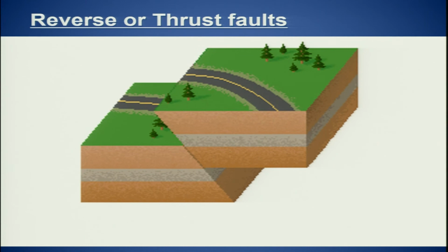Now coming to the reverse fault deformation. So please recall the section which I was showing from the Kobe earthquake, that we have the block has moved up and we have the high angle fault, and this block has moved up, and so you can show the direction something like this. Okay, this is down, and this remains the stationary wall, or we can say the foot wall, and this is your hanging wall.